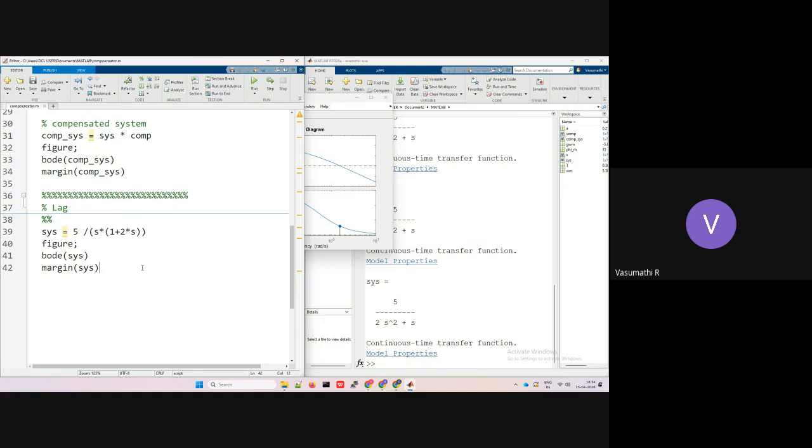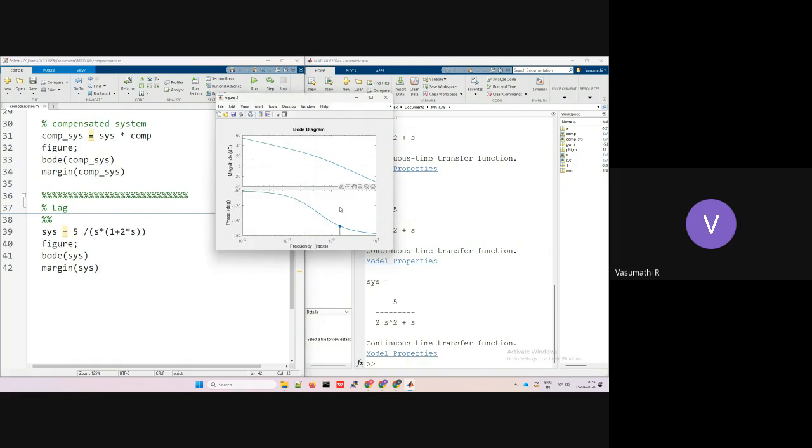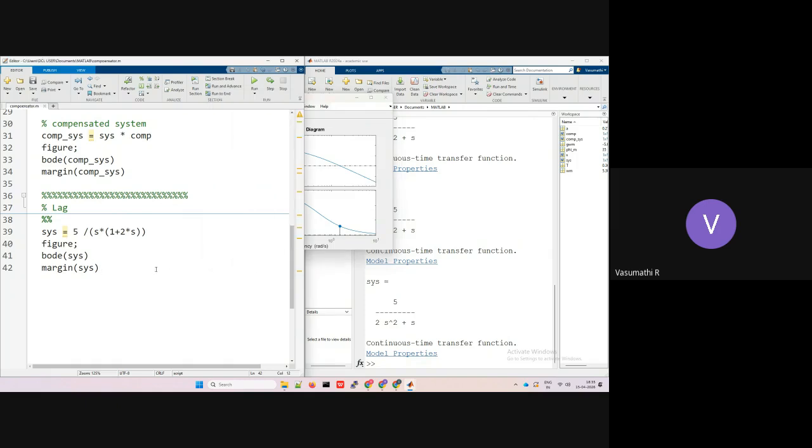Fine. Back to our problem. It should be 40 degrees, and there are no other requirements in this question, just a steady state error, which they have given and we already satisfy. Now we are trying to improve it to 40 degrees from 18 degrees, right? So right now the phase margin of the uncompensated system is 18 degrees. In this question, they have explicitly given that you use a lag compensator to do that. Most of the time it will be given, even if you are asked to do it by hand.